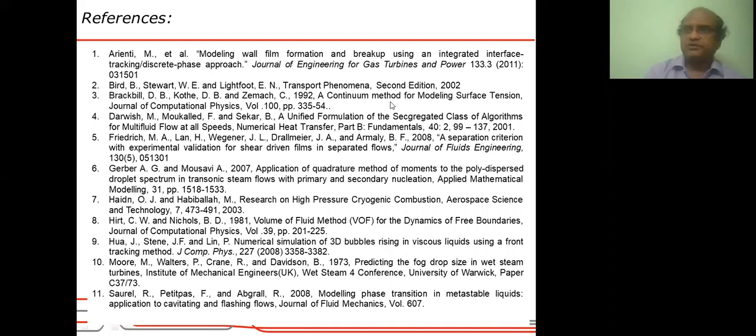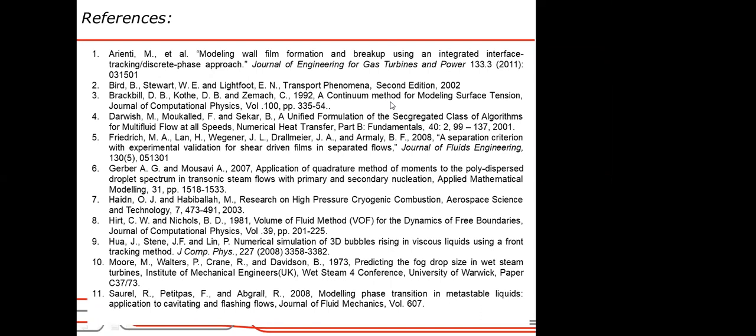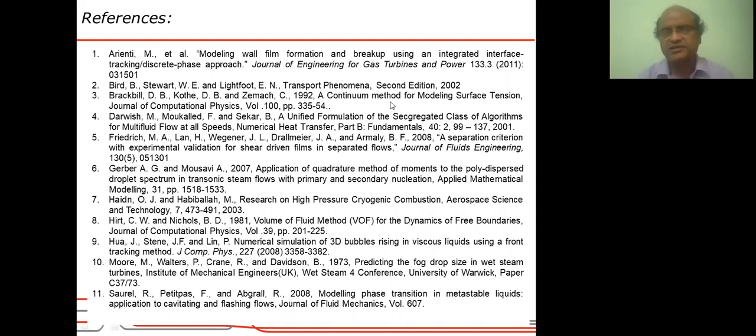That is why in old kerosene lamps with a glass cover, you see the soot particles getting deposited on the cooler side as it goes up. The glass surface is cooler than the incoming stream, so the soot particles from the incoming stream go to the walls and deposit. This is called thermophoresis. Then there is something called electrophoresis, which we will see in the session day after tomorrow. There are also certain additional terms added to take into account the virtual mass force, Saffman force due to velocity gradients, and so on.